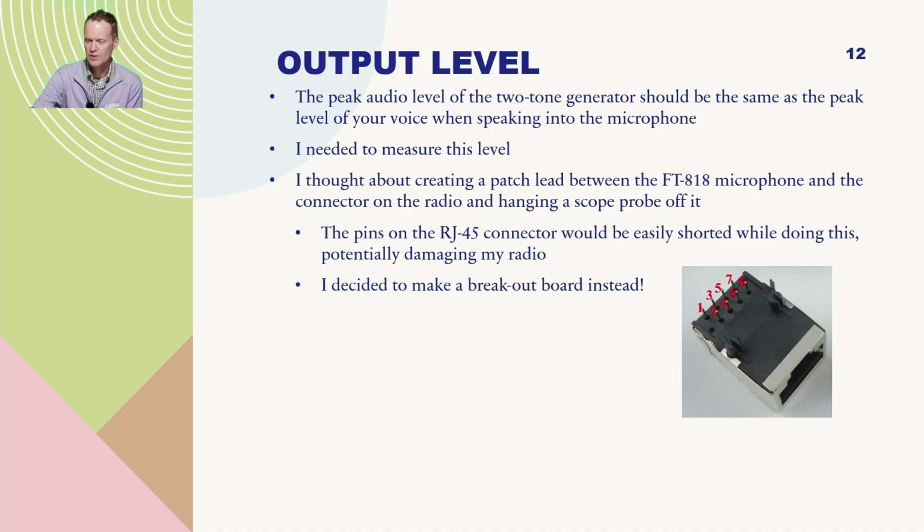So the second requirement was the output level of this two-tone generator. The peak audio level really needs to be at about the same level as the peak of your voice when you're speaking into a microphone. And I needed to measure this level. I had no idea, when I speak into the 818 microphone which I have here, what the level was going into the radio. I knew it would be fairly small, but I didn't know what small was. So I needed to measure this.